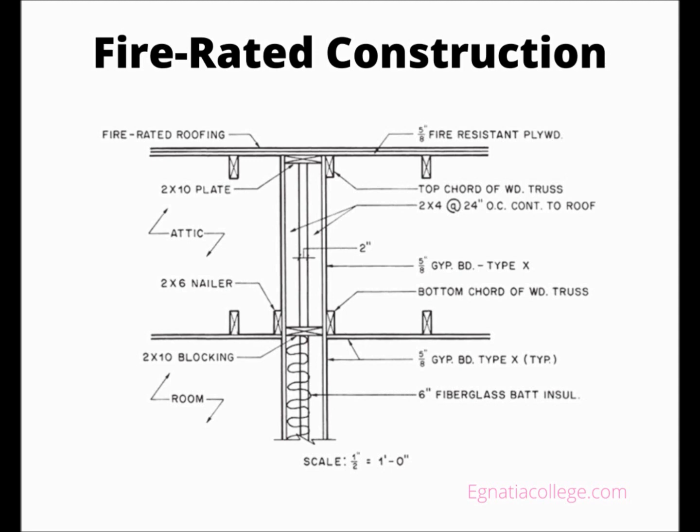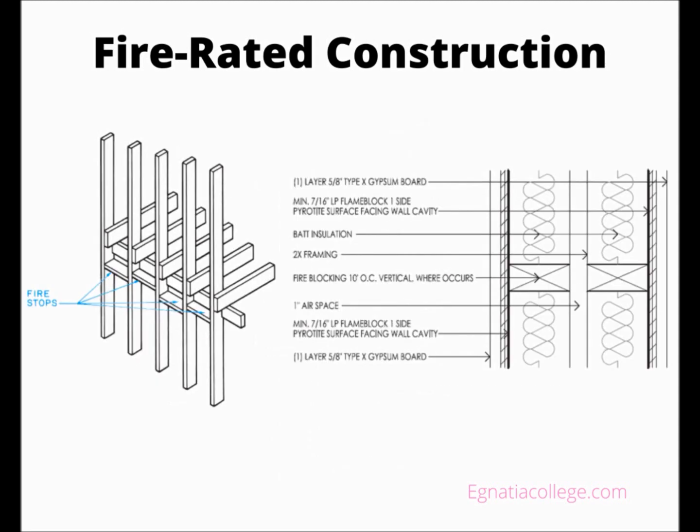This usually means that the roofing material resists fire for as long as the party wall does. For example, if the party wall is required to be a 1-hour code wall, it resists fire for 1 hour. The roof must be covered only with material that also resists fire for 1 hour.